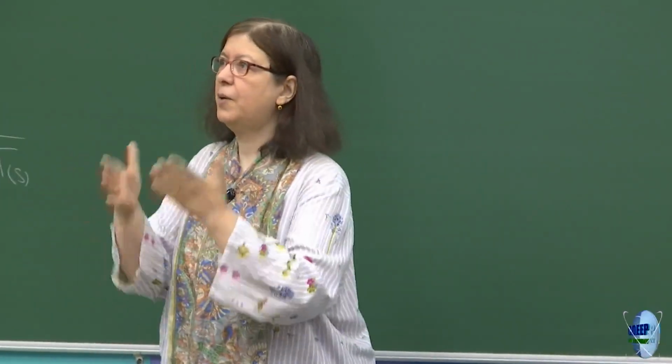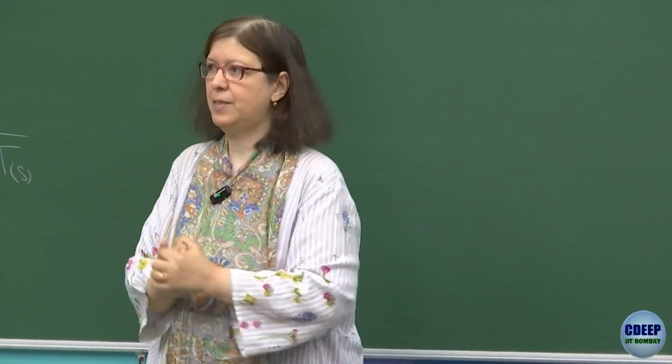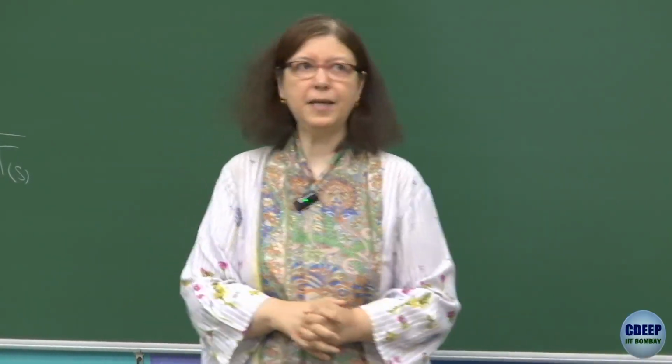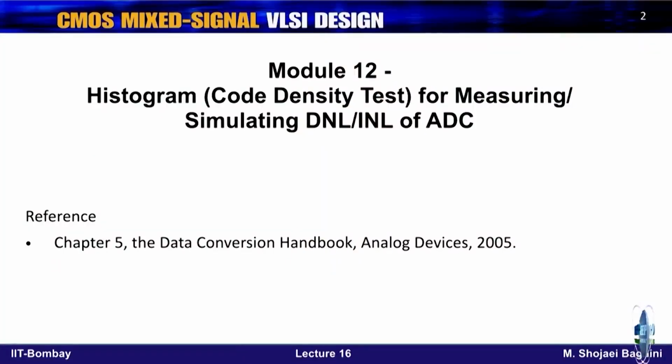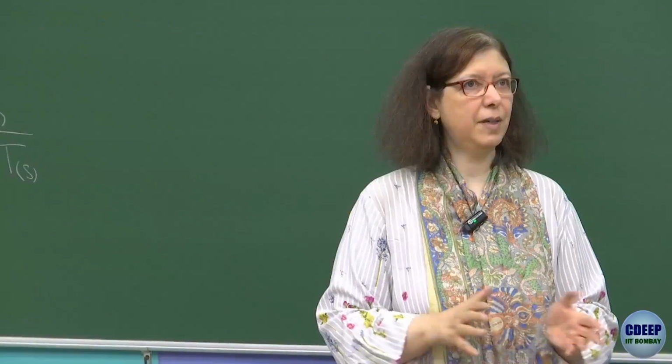One is about how it's actually practically possible to measure INL, DNL. You can measure by simulation as well, of course, Monte Carlo simulation before fabrication, but this is actually post-fabrication. And this is one of the basic methods. That's why it's good to learn about the basic methods first. Because this is almost like a static test, the input will be a very low frequency input.